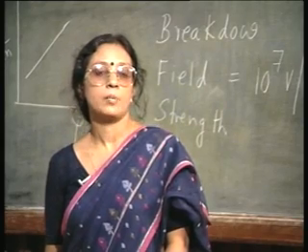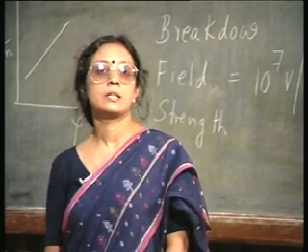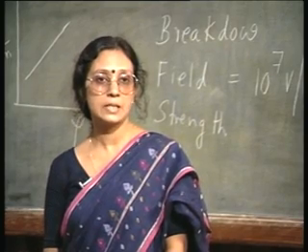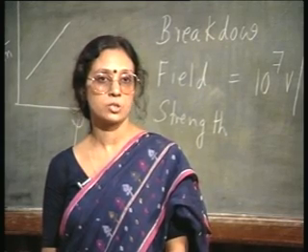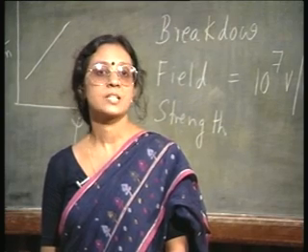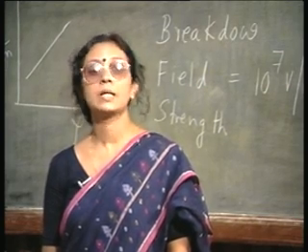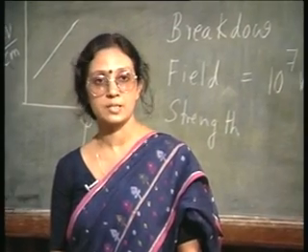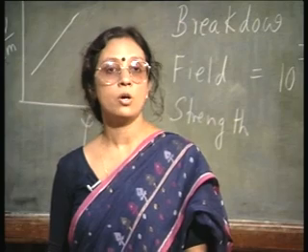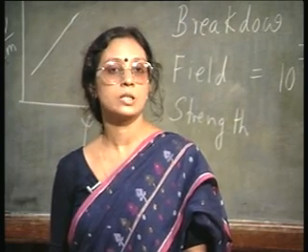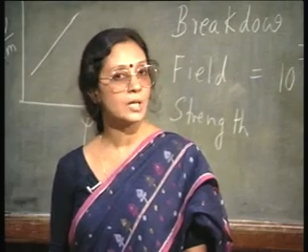So, this is about the oxidation of silicon. Let me emphasize once again that thermal oxidation in silicon is the best, yields the best oxide. The oxide properties are the best for thermal oxidation. That is why thermal oxidation is the standard processing step in VLSI technology, not the anodic or plasma oxidation, even though they can be used. They are used for other purposes like diagnostic tools, but definitely not in forming the gate oxide or even for isolation and masking. One does not readily resort to anodic or plasma oxidation. They are thought to be not VLSI compatible, even though they may have other uses.